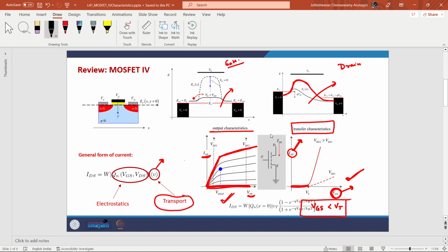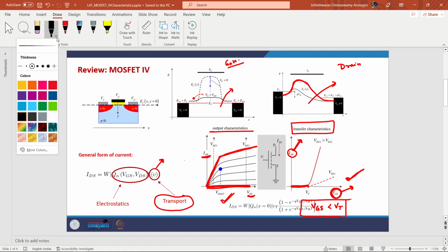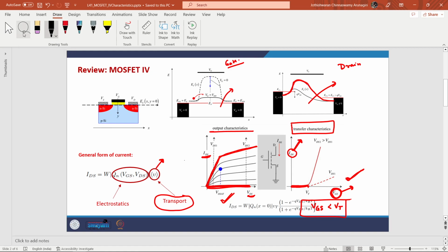In that, I am getting some high threshold. Suppose I am taking voltage from 0 to 2 volt for a two probe device, like source, drain, and channel. I am getting VT around 1.6 for 0 to 2 volt. My question is how this VT varies, maybe it is because of material property or maybe some channel length.